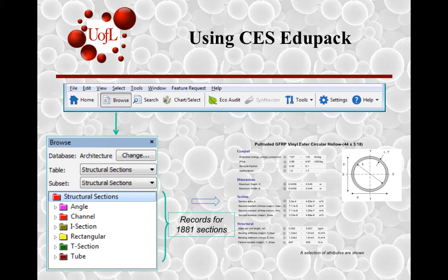How much energy is consumed, and from a sustainability perspective, if that is to be factored into a design, doesn't matter what your political viewpoint is in terms of the Green Deal, but as a design engineer, you can satisfy design constraints provided by a customer based on sustainability metrics. Dimensions also, in this case, are provided, and there are ways to specify those design constraints in a design. And then under section, you will have different options in terms of what the section area limits are based on these characteristics for that material.